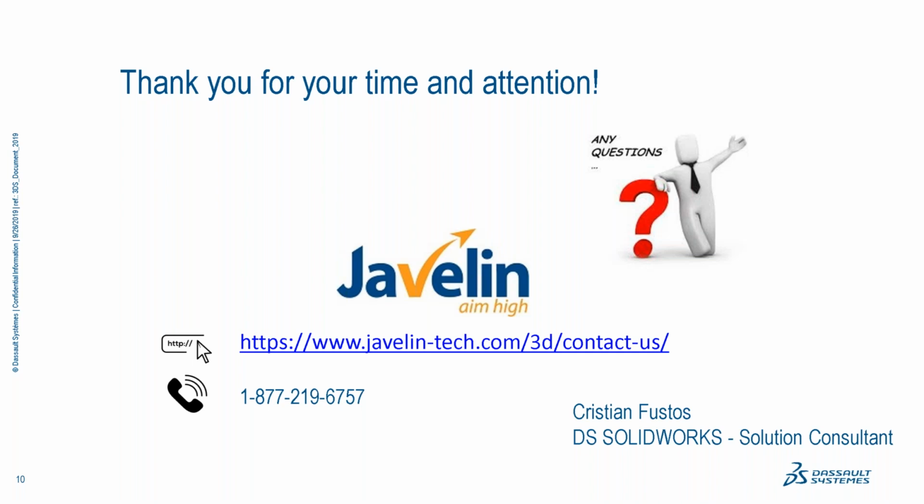Another question that we have from the audience is, do we still have to manually maintain the revision in the file name? Absolutely not, because SOLIDWORKS PDM Standard is completely integrated with SOLIDWORKS and Windows Explorer. You can just add that information to your data card and have the system automatically manage the revision scheme for you in the background. So the users don't have to have any type of control. They don't have to remember to revise the file. The system will do that automatically for them.